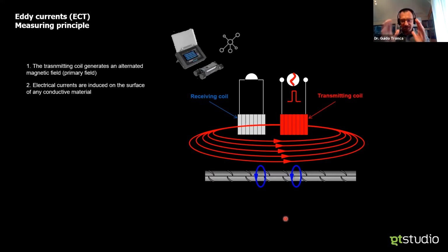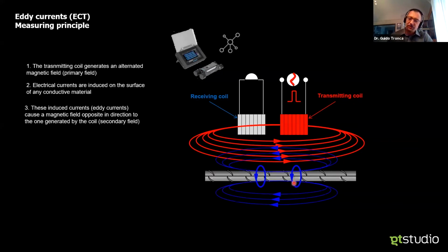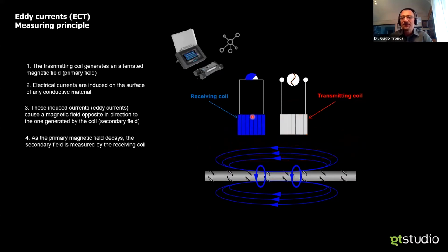So we are specifically onto conductive body, specifically ferromagnetic conductive body. When an electrical current runs over an elongated object, we know that a secondary magnetic field is generated. Hence, this is the quantity in terms of voltage that is related to the induced magnetic field that is measured.